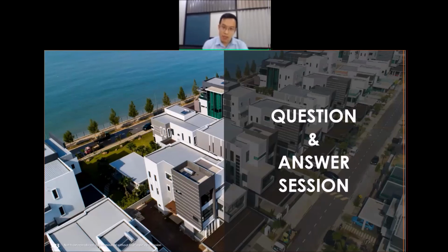But another limitation is that sometimes it will not be big enough to cut the whole cladding. So you might want to consider another tool, which is what we call a thin snipper or shear cutter. That is what traditional people use to cut on site, and it's actually much more preferred compared to other types of power tool. Another one that is lesser known is called a Nibbler. You can search online, Nibbler, right? This kind of tool chips away the steel bit by bit, and it can also provide a cleaner cut. You can also do some curve cutting.